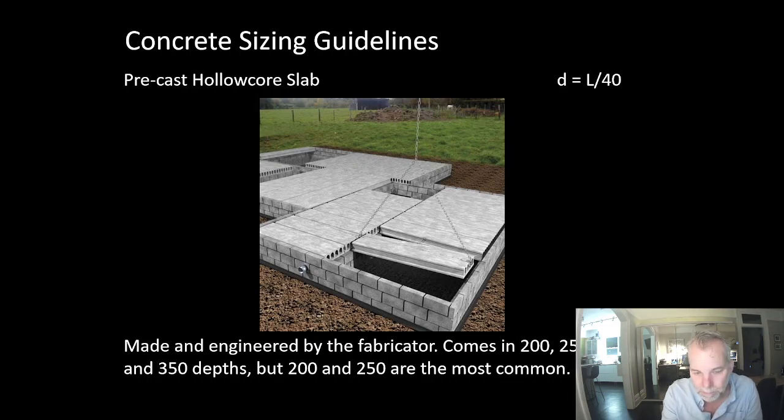But the single biggest problem in my mind with hollow core precast is that even though you are reducing the concrete quantity, the global warming potential of the concrete you're using goes up, and it goes up fast. You've taken 50% of the concrete out, but the global warming potential of the concrete you're using is double, so it's comparable to a solid slab. The reason is they need this concrete to cure fast, and the way to do that is to use more cement. And cement is the constituent element in concrete that has the most global warming potential.